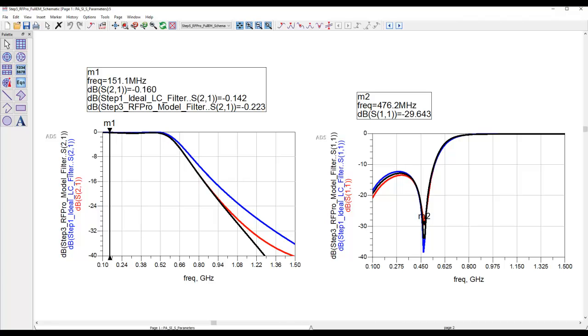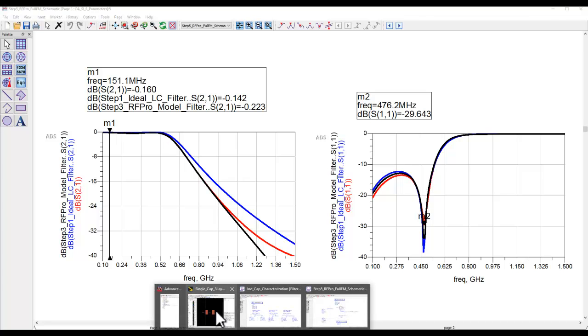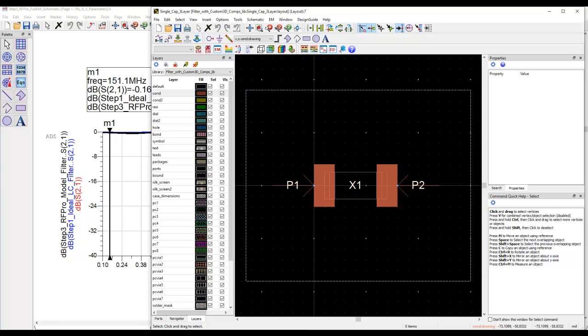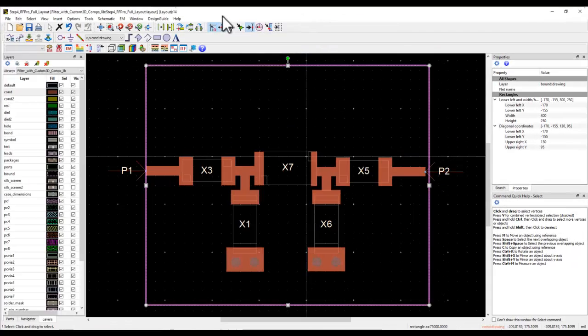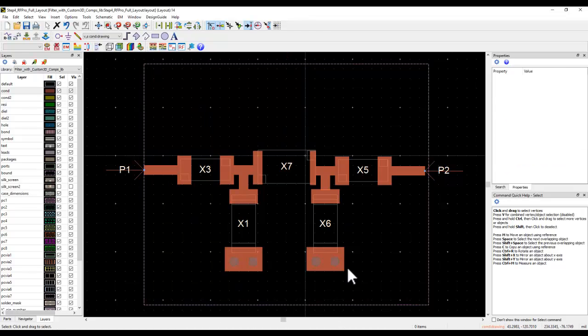So now I can confidently say that the layout which I was hoping to design is completely done because we ran a full 3D FEM simulation, and we can proceed for Gerber file generation and the coil winding and then assemble our PCB and test it out with a network analyzer and then compare the response.